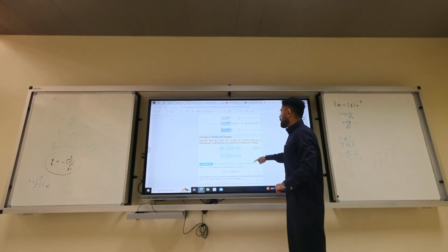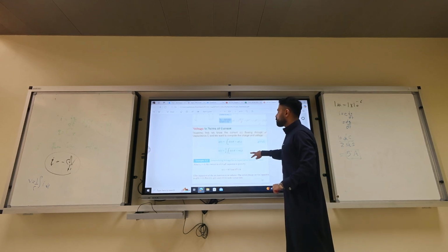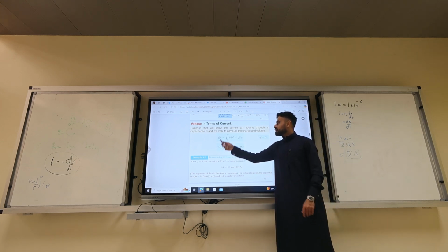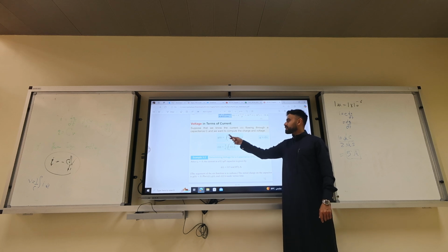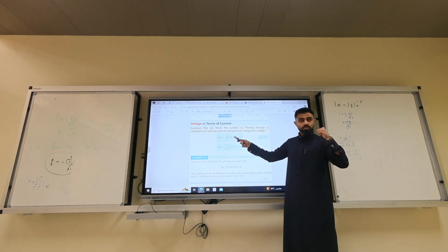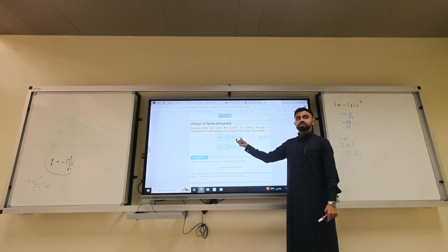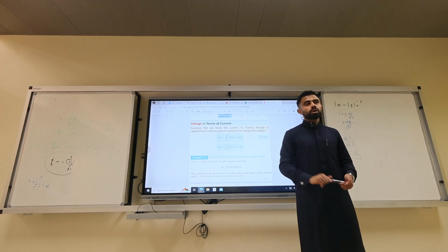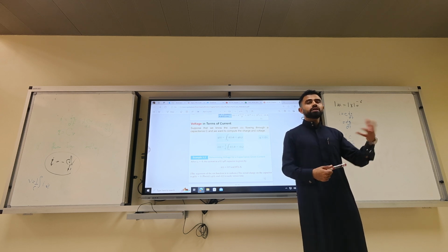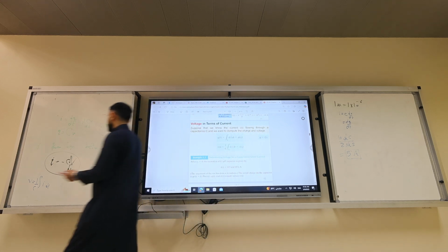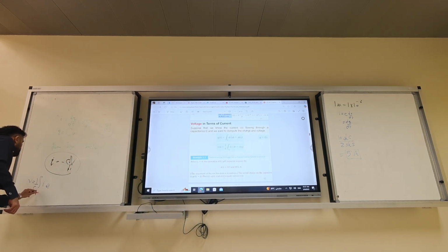If you solve this equation, you have to not forget about the initial conditions. So to get the charge is actually the integral from t naught to t plus the initial charge that was already stored. Sometimes the initial charge is not 0. Sometimes it might be 1 coulomb already stored. So you have to familiarize yourself with the initial conditions. So to fix this equation, we need to fix the limits from t equals 0 to t naught, and we need to add what?